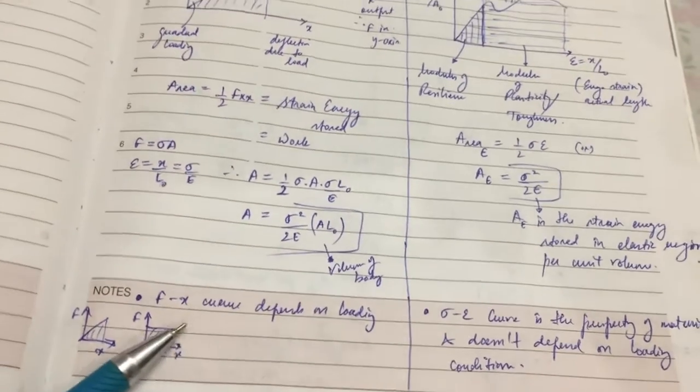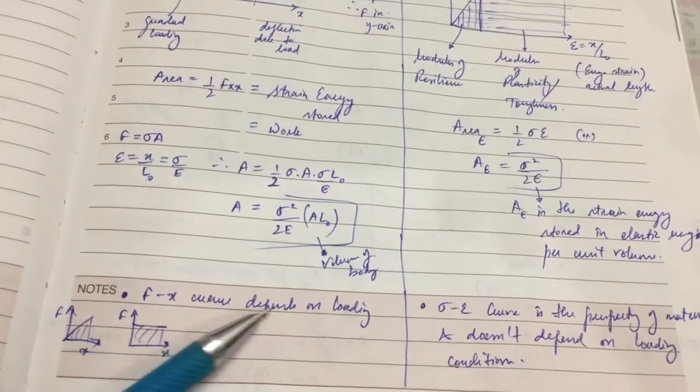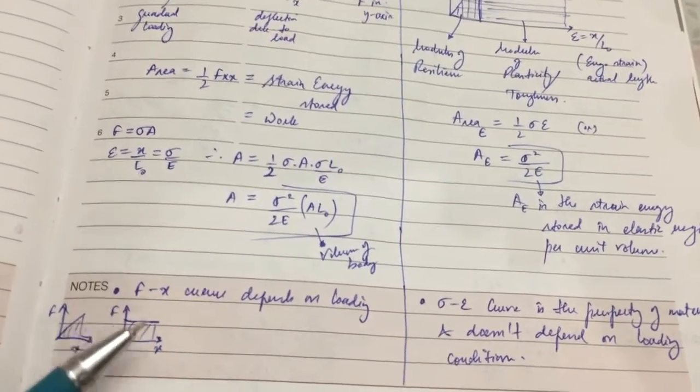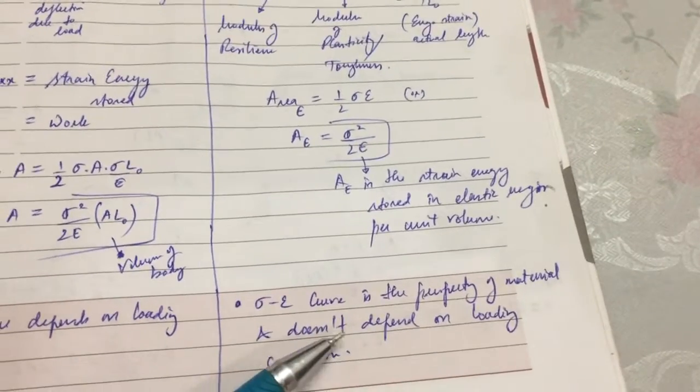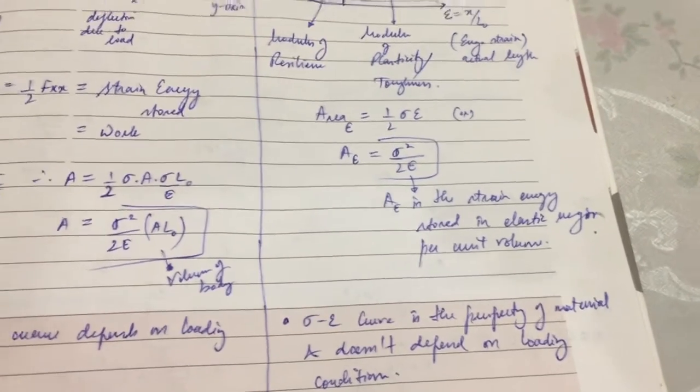Okay, so this Fx curve depends on the type of loading, gradual, sudden or impact loading, but the stress strain curve is the property of the material and it doesn't depend upon the loading condition. Okay,